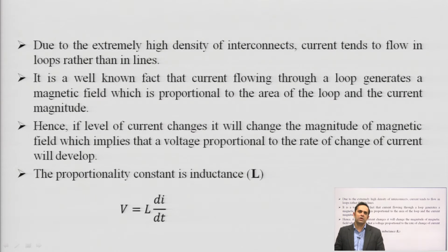So, the way an interconnect travels inside an IC may not always be in a straight line, but in the form of loops, and when current flowing through these loops changes, the amount of magnetic field produced is also going to change. The orientation of this magnetic field is also going to be different. So, the value of inductance becomes more and more difficult to estimate, but it is going to exist, especially at very high frequency. This is the origin of inductance inside an integrated circuit.